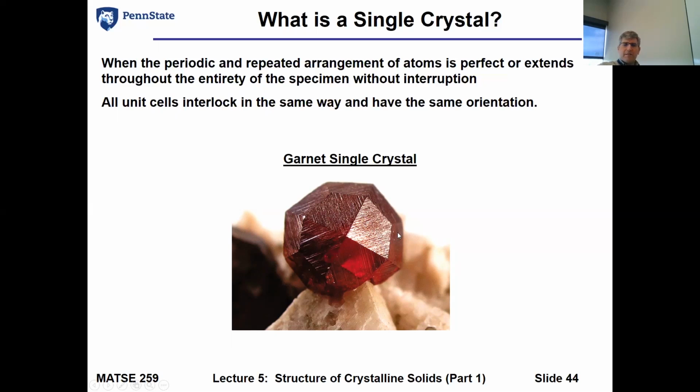Now, back to what we would use this type of single crystal for. We would use it traditionally to produce a laser. Neodymium YAG, yttria alumina garnet, crystals are used as a lasing medium for solid state lasers that we use for cutting in some cases, welding, cladding, and one of our newer ways of doing things, laser-based deposition and additive manufacturing. So at the core of what we have, at least previously, were these types of small crystals that would be used. They were actually small rods.